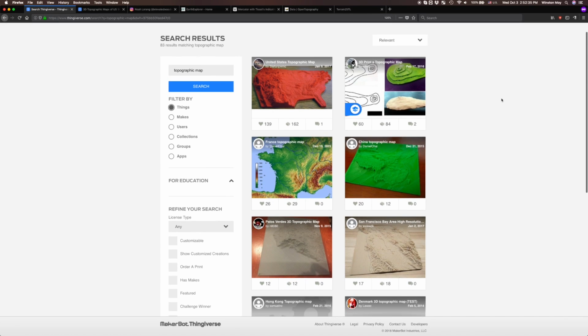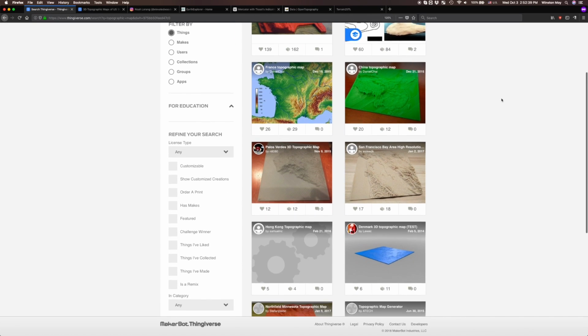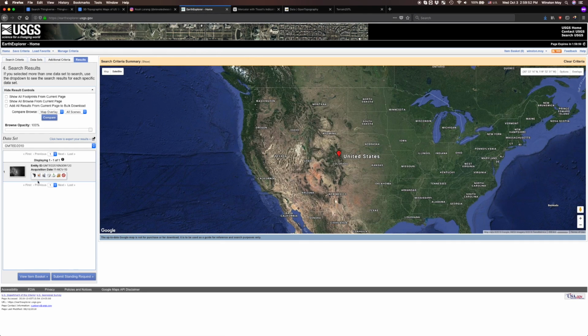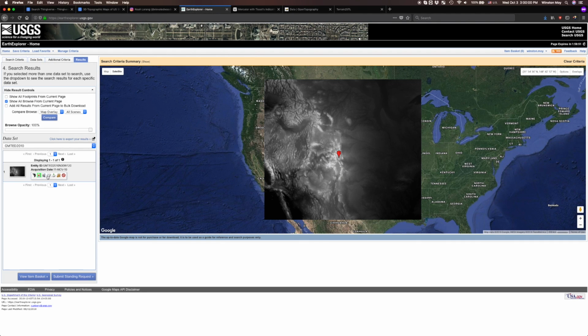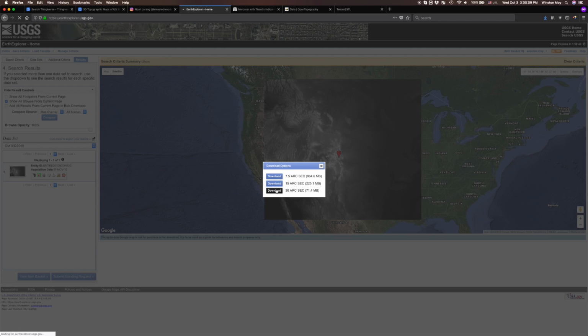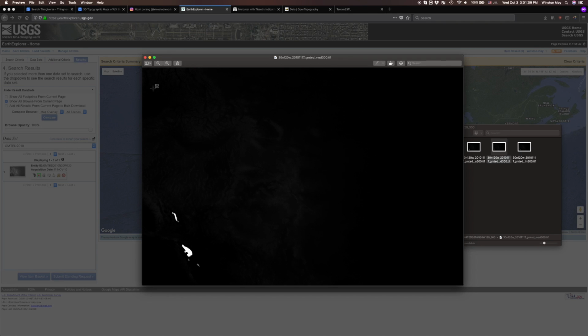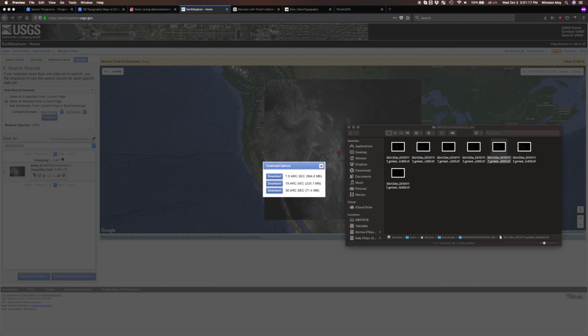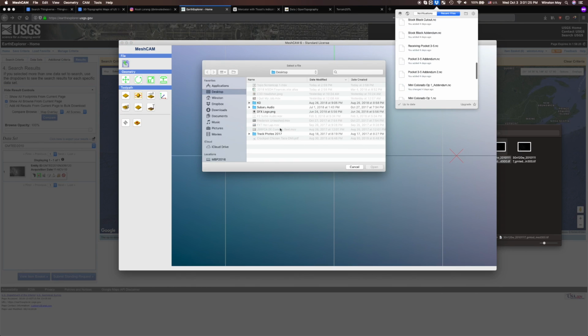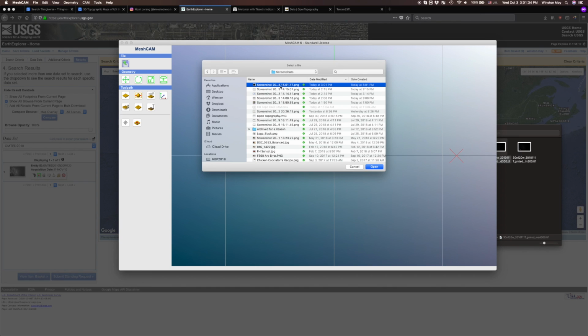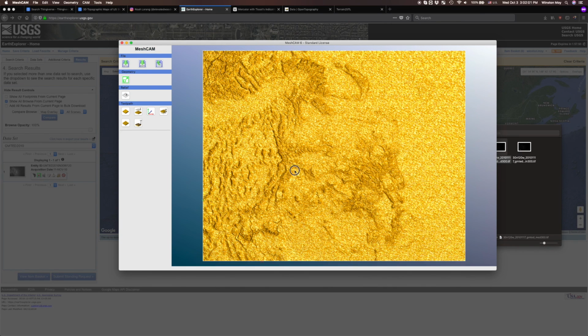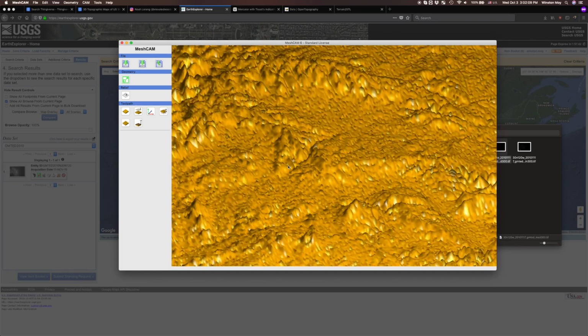The easy way is to find a pre-made STL file that you can carve directly. The hard way is to download a height map where grayscale brightness corresponds to elevation. If you can find a height map that's already cropped to your desired area, great, but you'll most likely have to download satellite data dumps available from organizations like the US Geological Survey, transform the distorted image into your desired projection system like Mercator, trim the image according to the regional boundaries of your choosing, and turn that cropped height map into a machinable file.